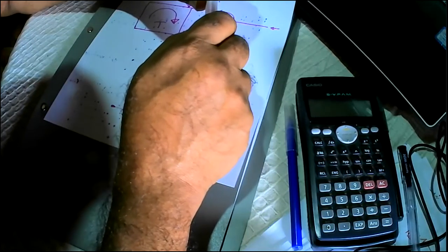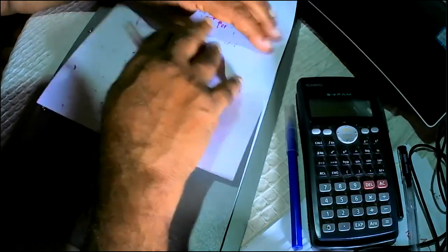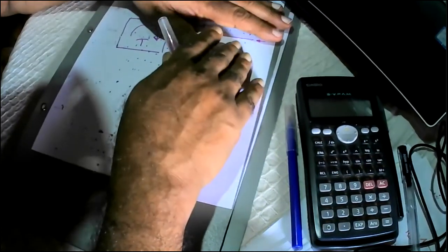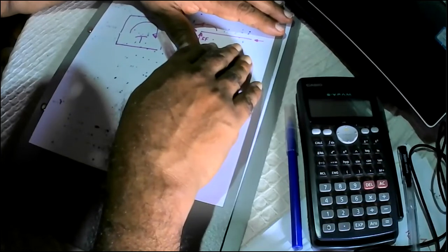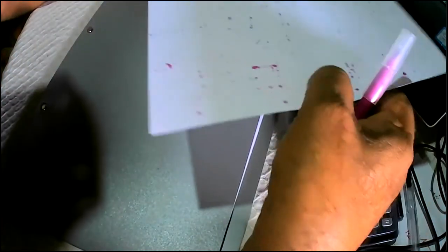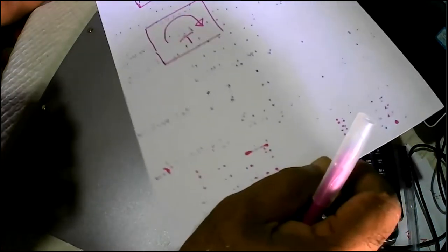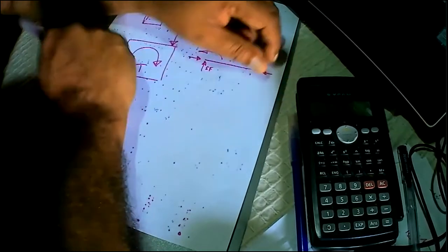And actually what we do is we say the slab behaves like a rigid diaphragm, and there's no deformation of the slab in its own plane. Which means the deformation of all the members in the building will take place like this. That means when the building is rotating, the whole building will rotate by the same amount. So that's the type of behavior that you get with rigid diaphragm behavior.